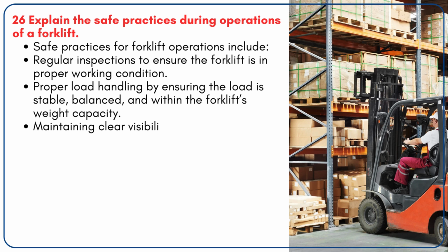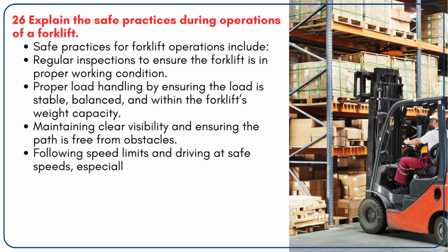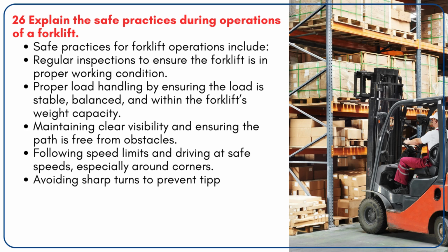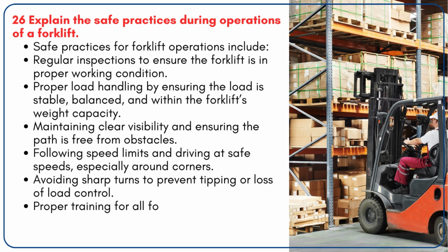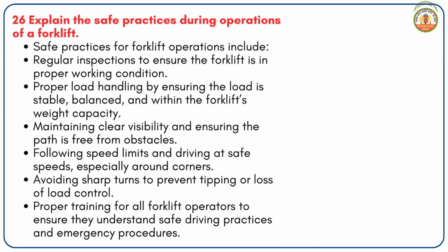Maintaining clear visibility and ensuring the path is free from obstacles. Following speed limits and driving at safe speeds, especially around corners. Avoiding sharp turns to prevent tipping or loss of load control. Proper training for all forklift operators to ensure they understand safe driving practices and emergency procedures.